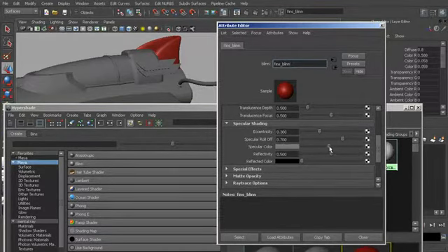Okay, and you get a good preview of what it looks like on our little swatch here. I can take the roll off down, which will reduce the specular amount. I can tighten up the spec by changing the eccentricity. So we can make something that has a tight spec, so something that's glossier if you want to do that, or you can make something that is more of a spread out specular look, which maybe is a little bit more of kind of like a metal.